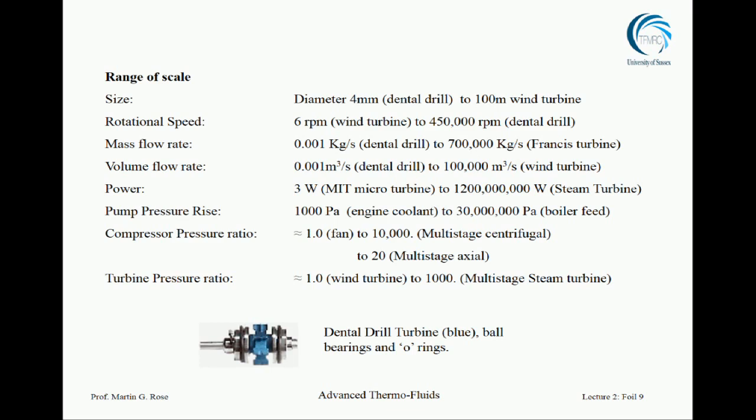But compressors can be put into multi-stage centrifugal, just as pumps can be made multi-stage centrifugal, so can compressors. And the limit is about 10,000 to 1 pressure rise. So an enormous increase of pressure. MAN in Zurich manufactures such compressors, and they're quite fun because the size of the impellers goes down and down and down, because the density of the fluid is going up and up. So the final stage is a little stage, and the first stage is a big one, and it's all because the pressure ratio is sky high.